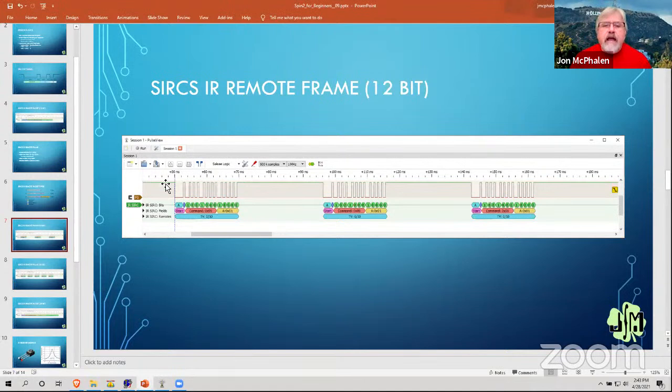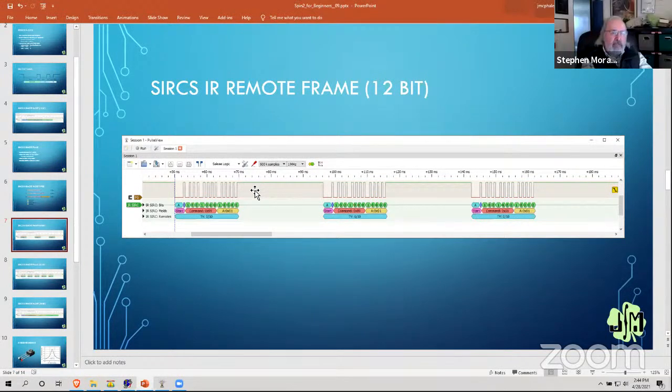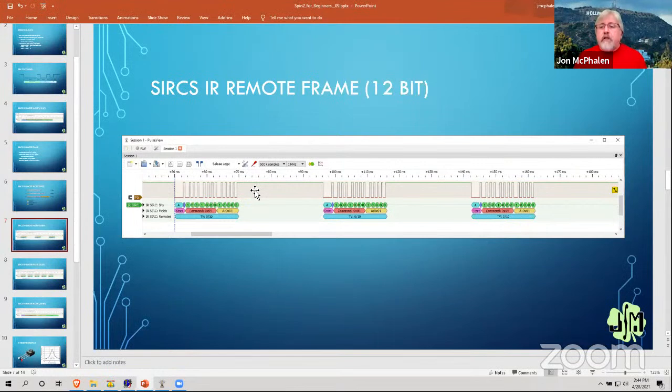So as soon as I have a valid code, I say, okay, I'm going to ignore the IR for 250 milliseconds. That gives me plenty of time to release a button. Now, as in the case I demonstrated a minute ago, when I pressed and held the button, the remote is just sending out stuff all the time. What that delay does is provide a timing of how fast or slow I increment or decrement. Yep, that makes sense. It's a tricky thing because you don't want it too long, because it is blocking.